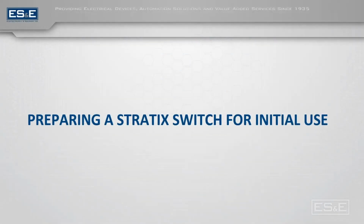So now we're going to cover setting up a Stratix for initial use. This is called Express Setup. For anyone who's messed with it before, it potentially can be frustrating the first time you go through it. So we wanted to make a clear and simple method for doing it. I like to power off the switch a certain way through the process because you kind of get a guaranteed result. The biggest thing with the Express setup is the switch boots. It takes some time, so just having a certain level of patience as you're going through the process.